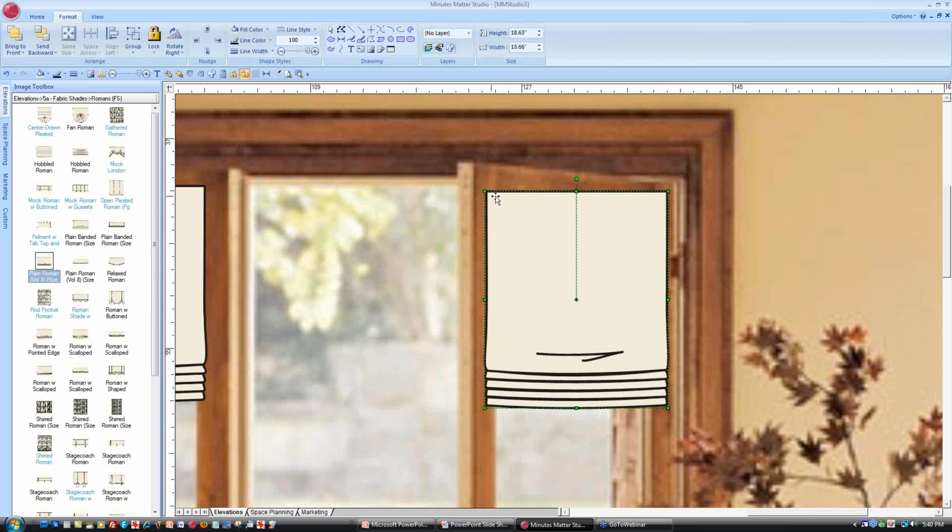In order to activate the red skew perspective edit points, double click and drag that top left corner up to match the angle of the door. This is at pretty much the center of the door, so it's going to stay pretty much level there. We can make it a little bit narrower and add a teeny little return to give it some dimension.